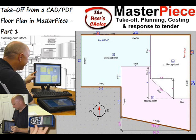In this part 1 video, we have looked at the basics of tracing round the on-screen floor plan and using the shapes created in the cutting plan. Part 2 of this video covers further aspects, including working with more than one floor plan image, for example, where there is a separate PDF for each level of the building, tracing rooms which have diagonal sides, and choosing which way to run the pile when a room has some diagonal sides and some vertical and horizontal sides.